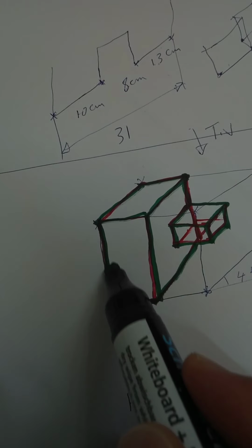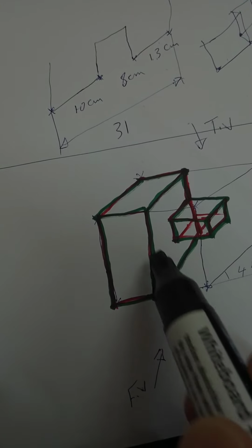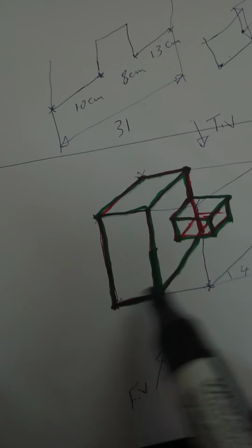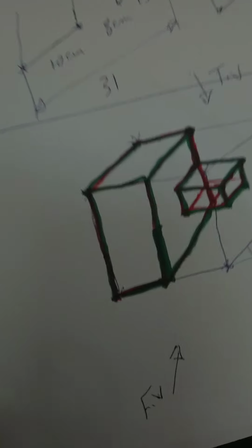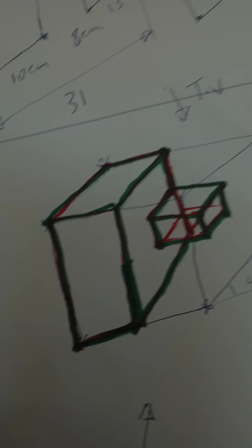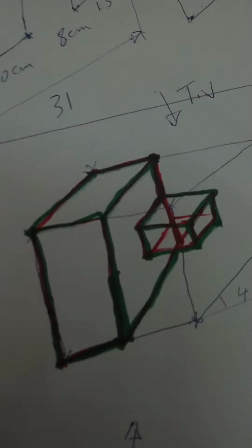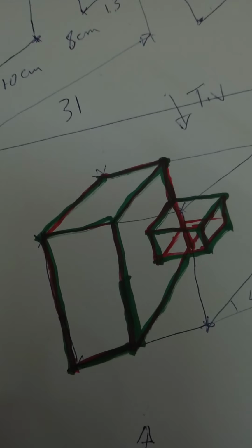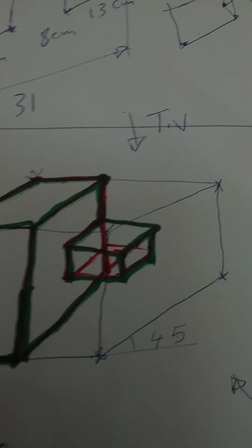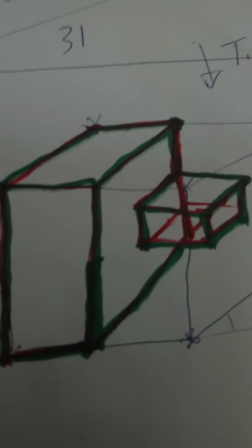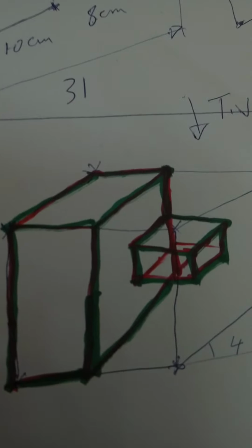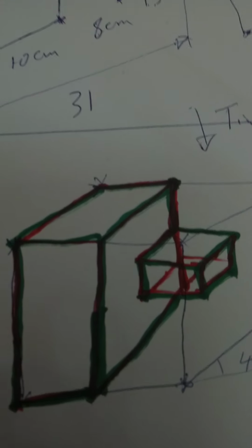As I mentioned before, we have to learn what the shared parts are for each projection plane. Given a projection plane, we have to know what the shared lengths are between the front view and right side view, the front view and top view, and the right side view and the top view.